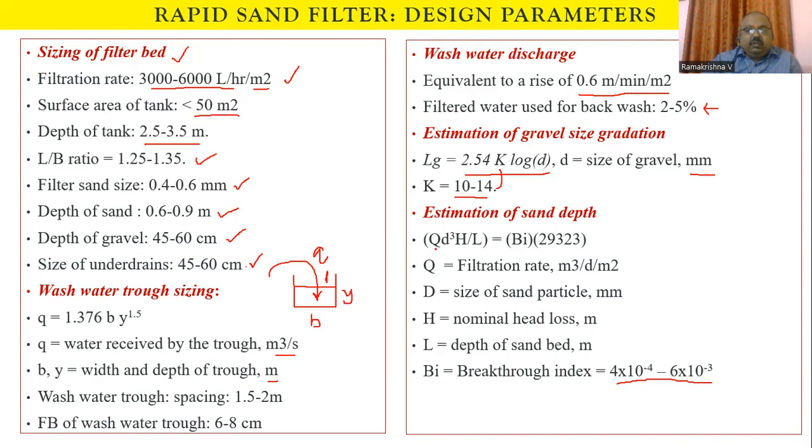So once we calculate the filtration rate and the size of the particle we adopted, and if we assume the nominal head loss, then we can calculate sand depth L by assuming the expected breakthrough index. Okay, so this is all about the design parameters.